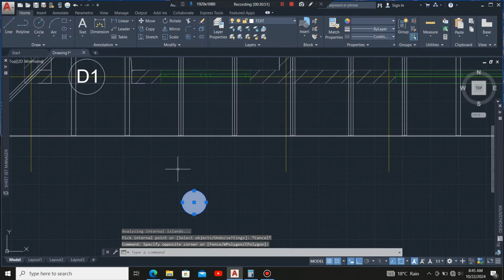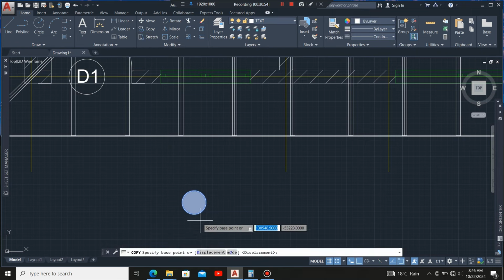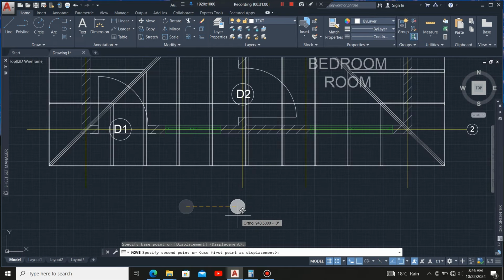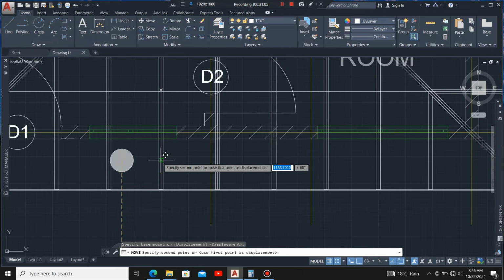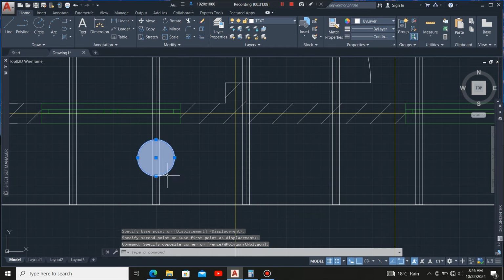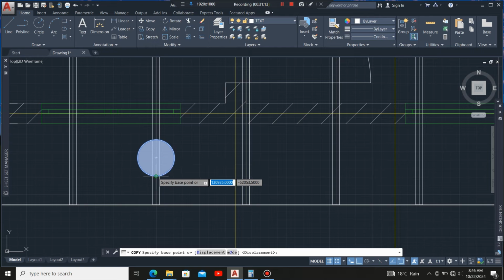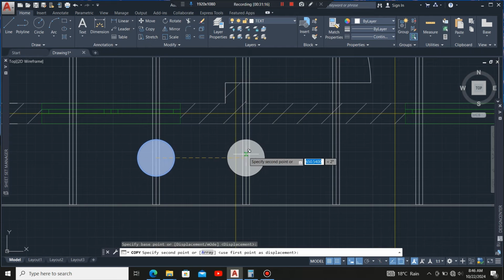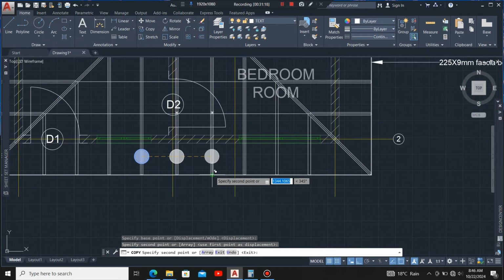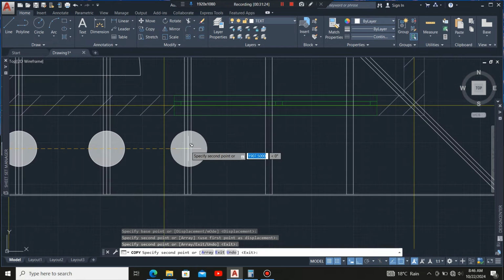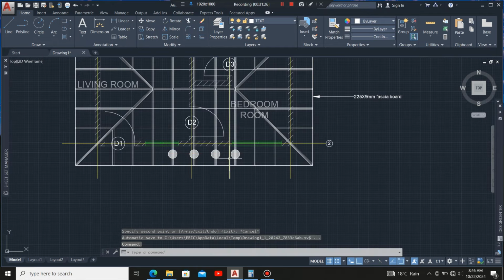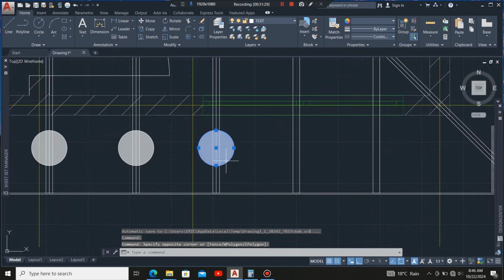So there is something I want to show you here. If I want to name these common rafters, I usually do it like this. I create this zero, then I give it a solid hatch, then I'll simply copy it to these common rafters. Let me delete this one.